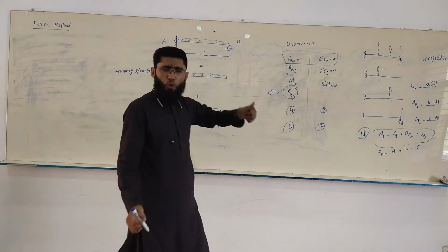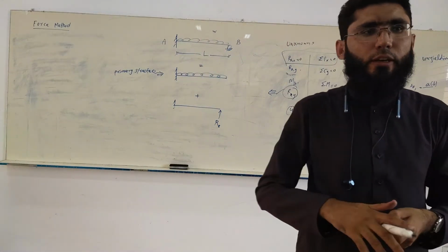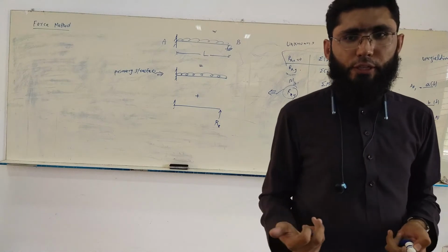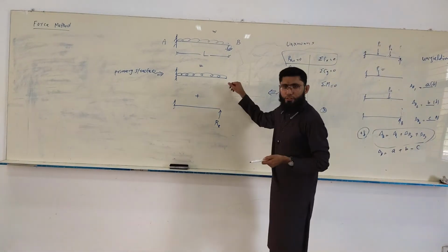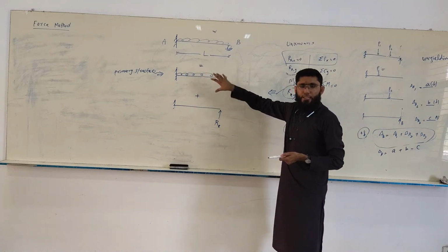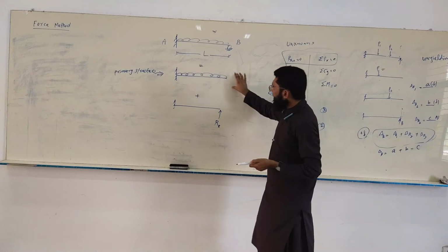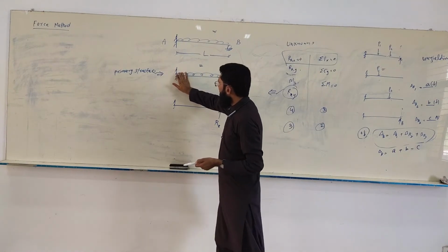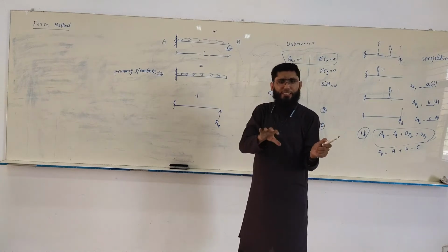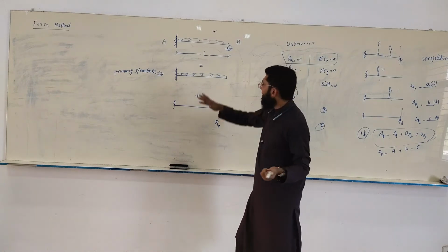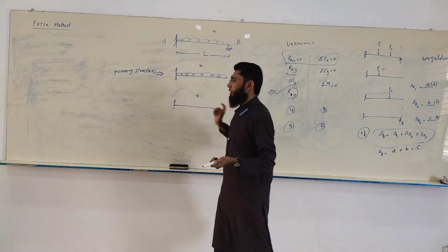So, of course, it has to be something determinate. Otherwise, there's no point in doing this practice, okay? So the problem was there was a redundant force, so you temporarily remove it in this structure, and then you consider it separately, okay? Now, this structure, without the loading, I mean, something applied on the structure, but the structure itself does not include loading. The structure is this support and this beam. So this is the primary structure, okay?